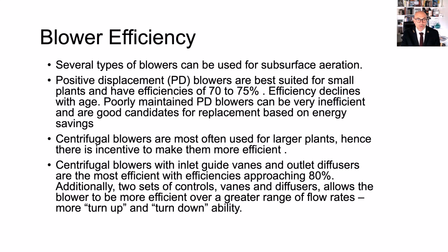And we have different types of blowers, and there's a whole blower taxonomy we could go through. But the important thing to remember is blowers operate by blowing air. They don't compress it, okay? The air compression only occurs if you impose a pressure drop at the discharge of the blower. If you take a blower, you put it in a basement, and you run air in and out of the blower, the pressure inlet and outlet is practically the same, okay? And we are in the same room.